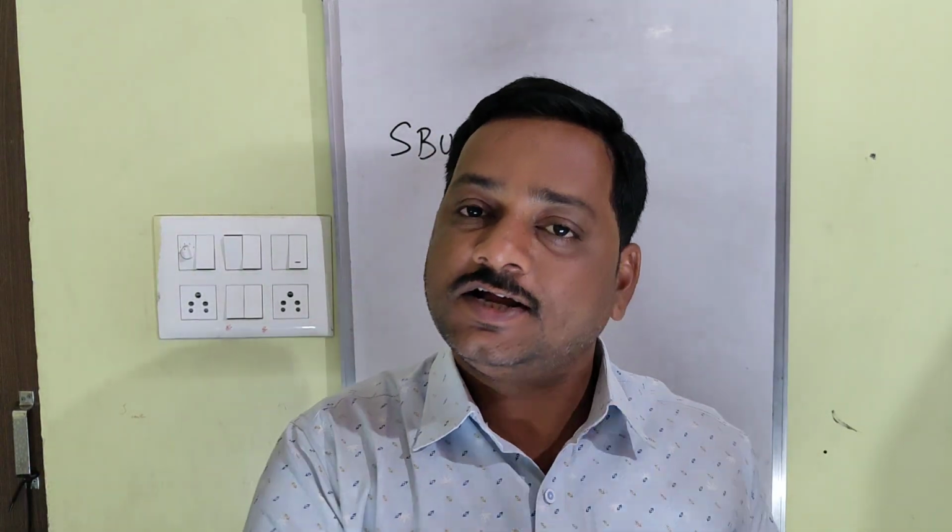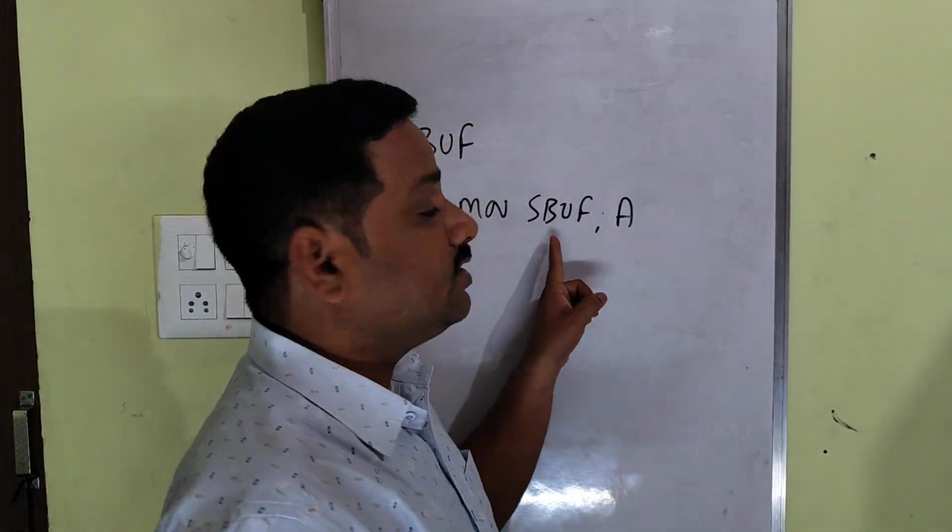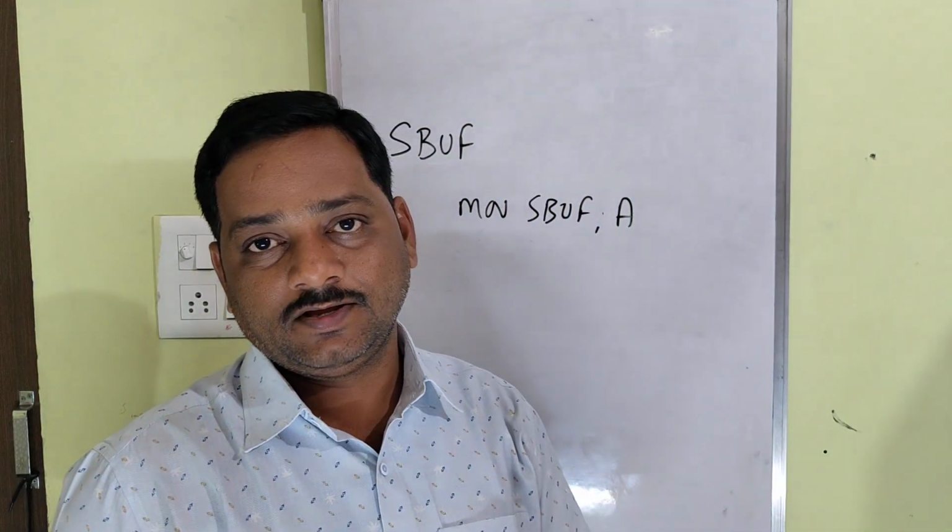And now if you want to receive, let's see how to receive the data. Someone, another system, is transferring data to the microcontroller, which is again received serially. When it receives the data, where it will be stored, that is the point you need to know. Whenever the data is received serially, it will again be stored in the SBUF register only.